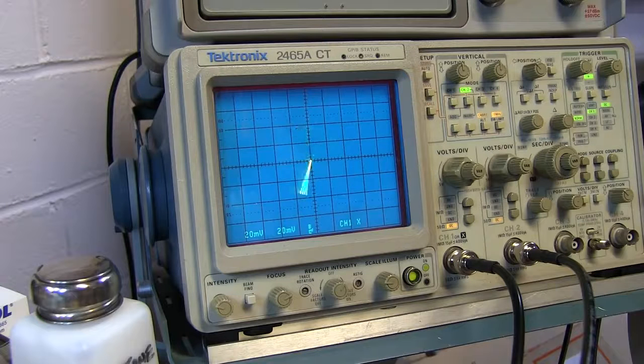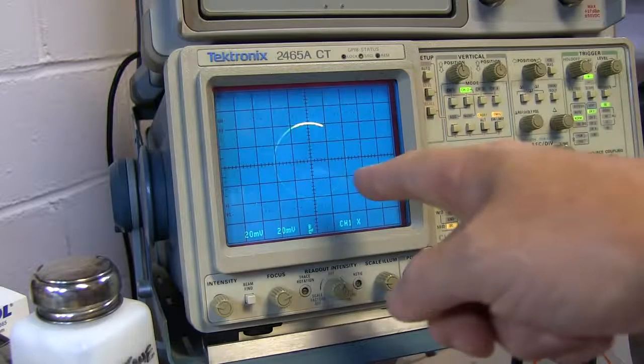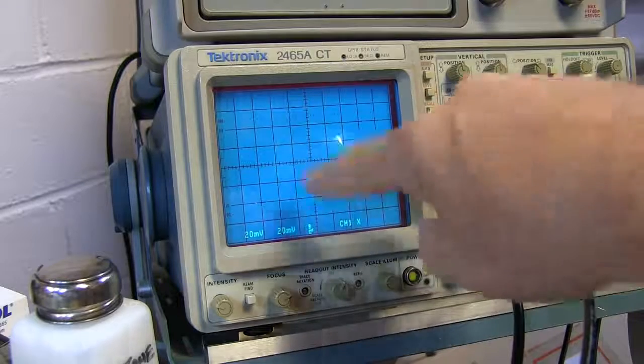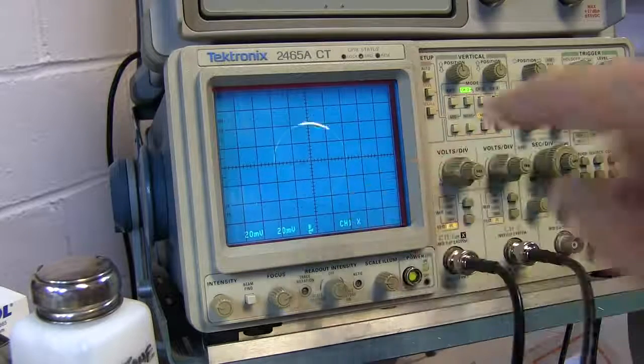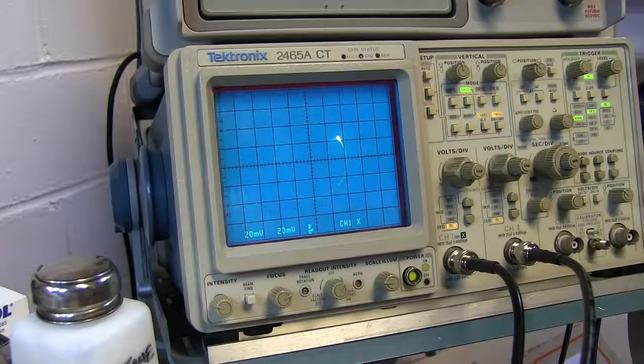Now, of course, FM means that we're varying the frequency as a function of our baseband signal. So if I bring that frequency offset back to 0, and I change my modulation type from AM to FM, now what we're seeing is an FM signal that has a 1 hertz baseband frequency. So I'm spending essentially half a second spinning in one direction where the carrier frequency is higher than the local oscillators, and then the other half a second spinning in the opposite direction when the carrier frequency is below the local oscillators.